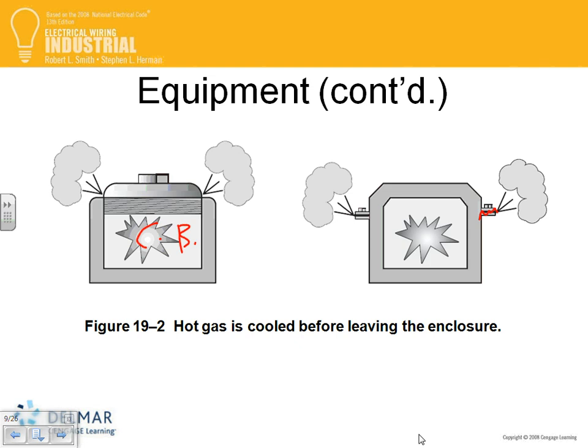So if I have an explosion in my circuit breaker and there is a gas over here, by the time this air escapes outside, the temperature of the air will be low enough that it's not going to ignite the surroundings. That's why they need the threads in hazardous locations around all the equipment. Even if there's an explosion inside it, it's not going to explode outside because it's explosion proof. It contains the explosion inside, but the air has to go somewhere. It escapes through the 5 threads, and by the time it reaches outside, it's low enough temperature-wise that it would not do any damage.